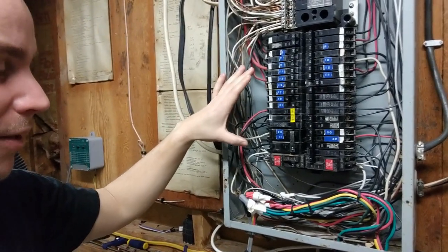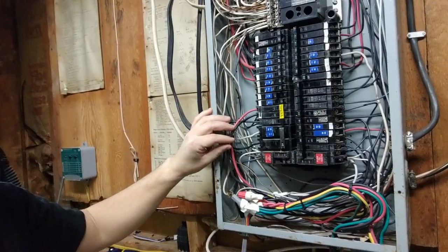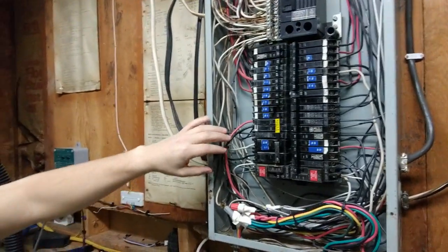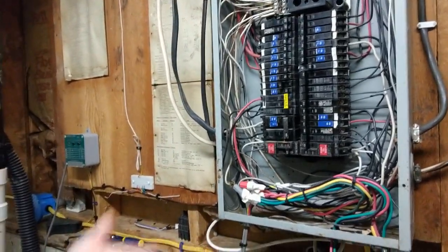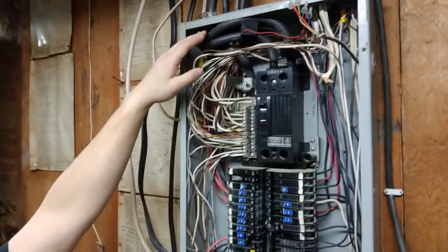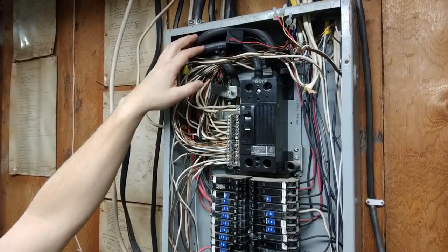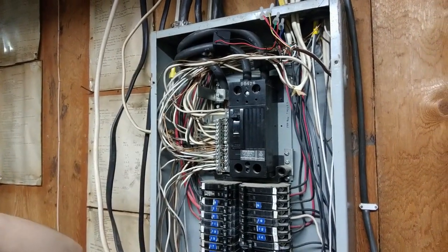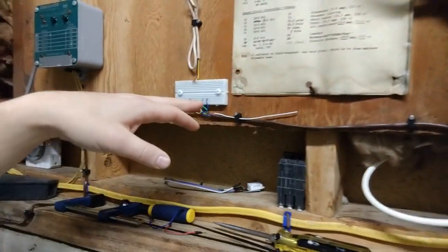Most of the time you're going to see power meters that will go on each individual branch circuit and display what is going on in all those, add it up, and display how much power you're using. So what we're proposing is that we would have only two CTs, which would significantly lower the cost of the hardware. So you bring it over, and it comes into a shorting block.